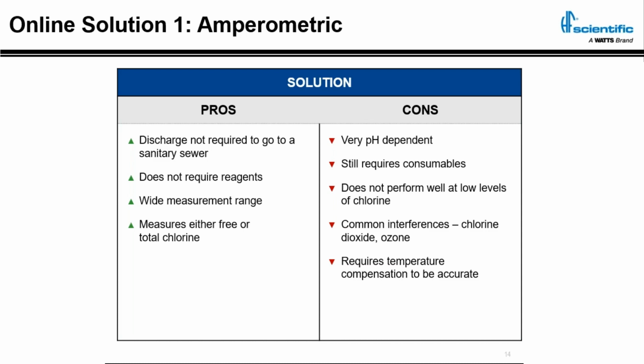And most of this discussion has been around the reagentless version of the amperometric, where you use a pH probe to measure the pH of the sample. But I have seen some amperometrics where they do use a reagent to adjust the pH of the sample so that the sample is hypochlorous acid rich. And I do tend to think that those work better.